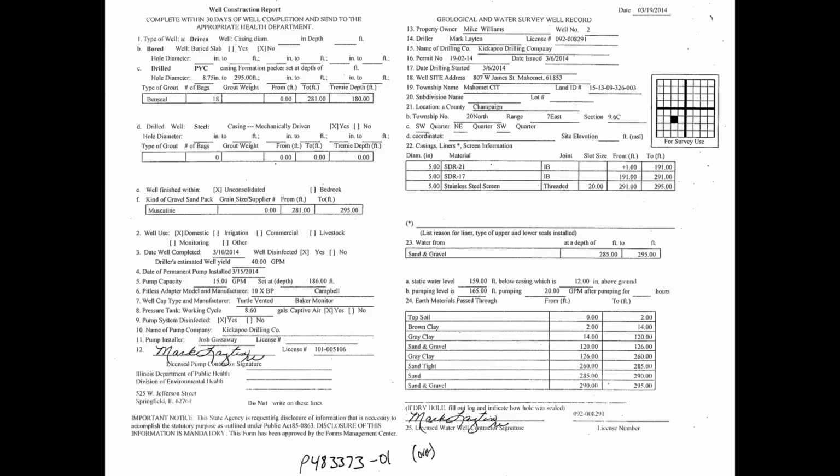So they hit 6 feet of sand from 120 to 126. They decided that wasn't enough, which is very marginal for a water supply. And then they kept going, and they hit deeper sand that, as you see, says sand, tight sand, and then sand and gravel. So when the glaciers melted and deposited all this material, the largest particles fell out first, because the velocity slows down, then smaller particles can fall out. So typically in a sand and gravel aquifer, the most coarse material is at the bottom. So that's why we see sand and gravel at the bottom.